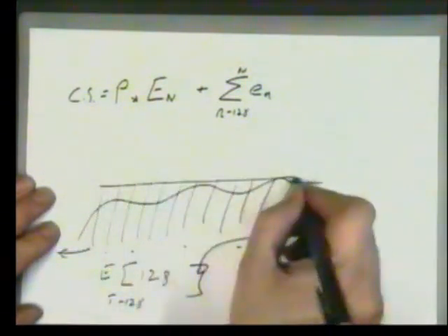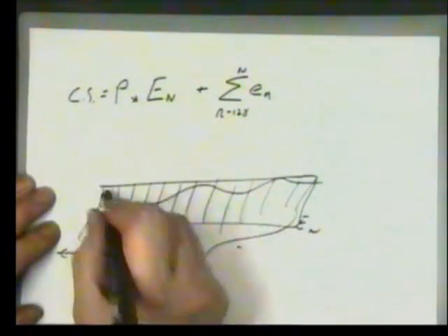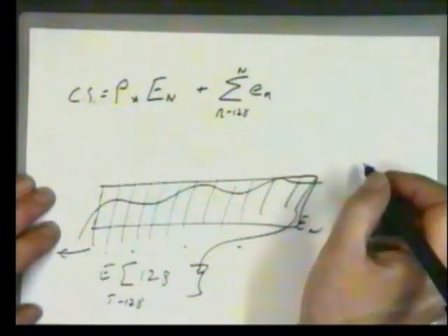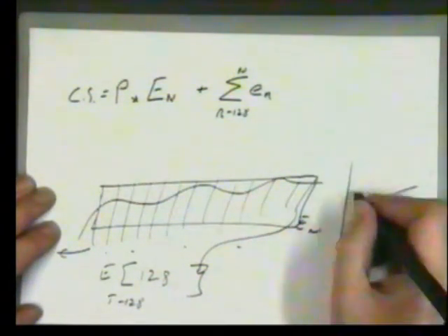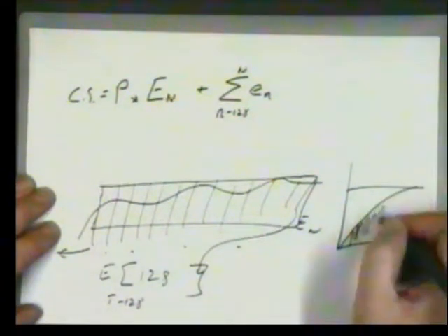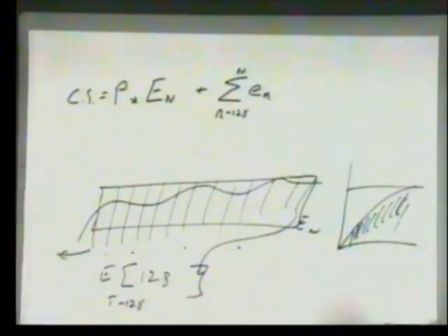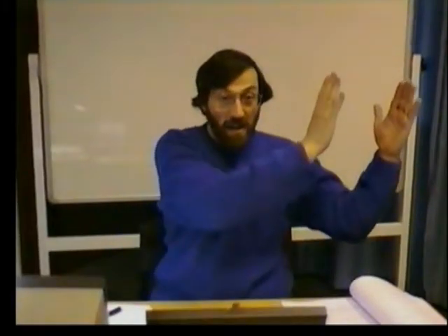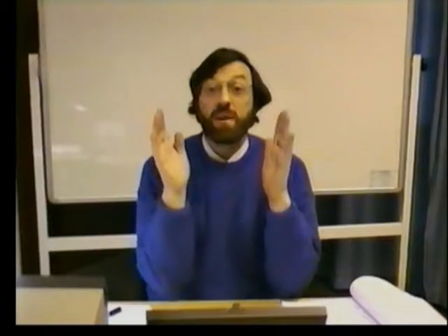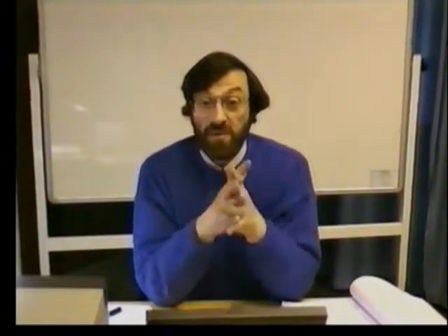If we only integrate over the most recent history, then we overcome the gravest problem of an I term. An I term went out of control because it integrated everything. If we use a sampled data system instead, so we have a moving window in time, we will only integrate our most recent samples, and doing that we can have a far more stable proportional integral controller.